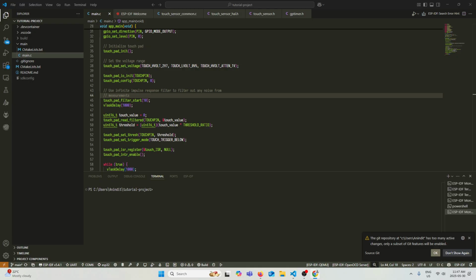Once you get the sampling frequency, you can sample the analog waveform, and then each of the sample points will be encoded with a certain discrete value or bit, aka quantization levels. And then the resolution will tell you the range of the y-axis, or the voltage levels.